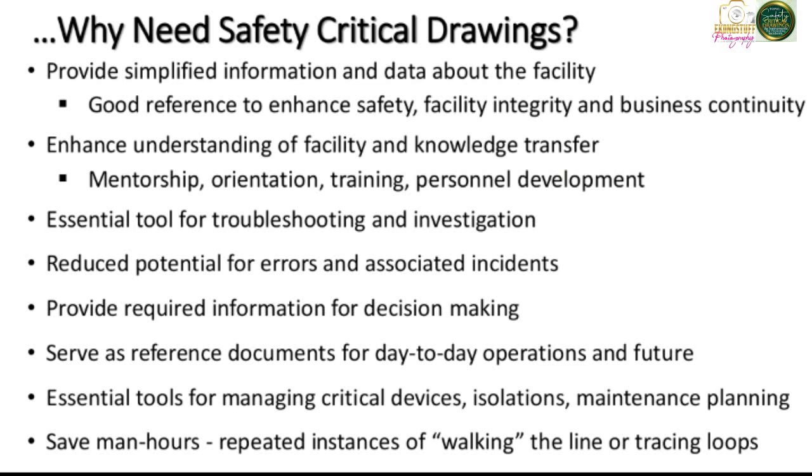And then think about managing critical devices. I've talked about isolations. Think about planning for maintenance. It is key that you have the right drawings that enable you to make the right decisions in terms of what you want to defeat, or what area of the facility you need to isolate. And if I isolate this, what potentially may be impacted?